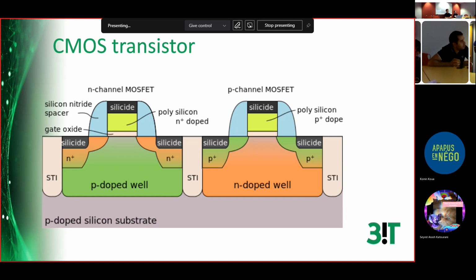This is your real device. This one is your dummy. That means you extend your LOD, and the STI is further away from your real device. These are dummy gates, not dummy transistors. It can be done with transistors, but you will have a DRC problem if you add more. You have to merge the OD regions. You don't have to; the DRC rule is for ODs which are separated by a certain value.